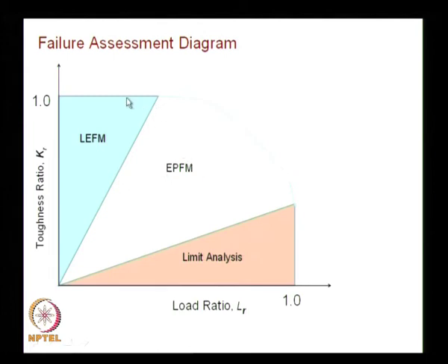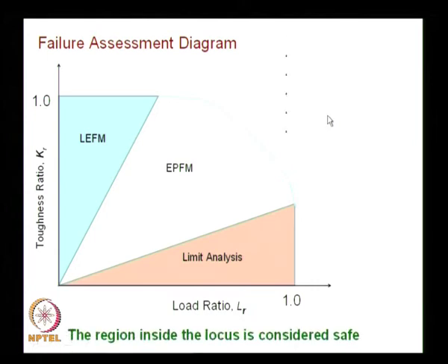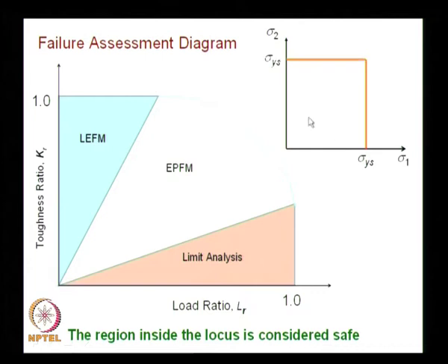See, what this graph says is, I can't have a straight line and another straight line meeting here. In conventional design, what have you done? You had combined loading of sigma 1 and sigma 2, and you will say yielding occurs when sigma 1 equals sigma ys, or yielding occurs when sigma 2 equals sigma ys, and this is the yield locus you get from your Tresca yield criterion.